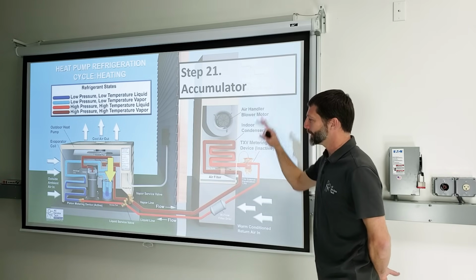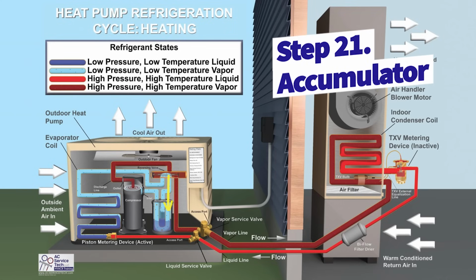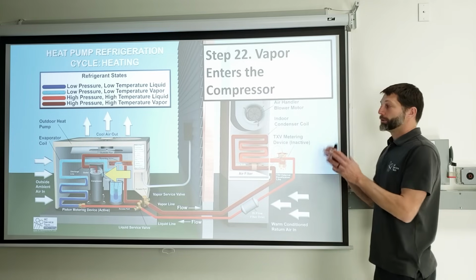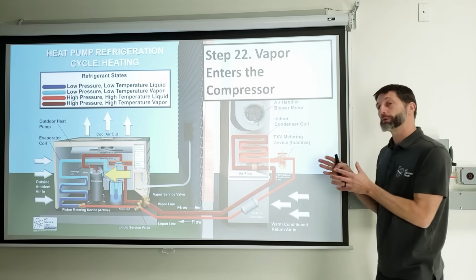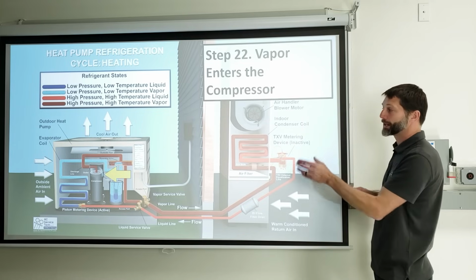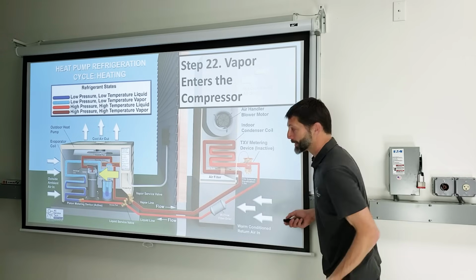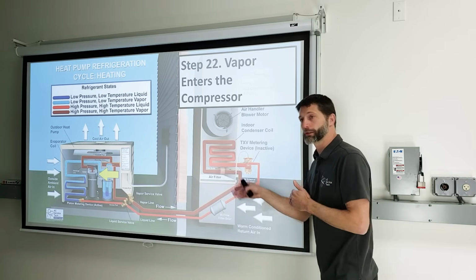This is a ducted heat pump unit in heating mode. So anyway, you have your refrigerant entering into the accumulator tank, where the accumulator's job is to store any liquid refrigerant, and its job is to also make sure that only vapor refrigerant exits the accumulator tank and enters into the compressor. So it's very, very important to have an accumulator on a heat pump, just because that outdoor coil might have frost or ice on it, and if you didn't have that, you would basically immediately be killing that compressor with liquid refrigerant entering into it constantly.